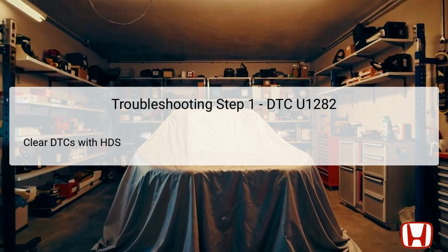Clearing DTCs prepares the vehicle's system to run a fresh self-check upon restarting, making it easier to identify new or recurrent errors. Be sure to connect the HDS properly and follow the prompts to ensure that all codes are cleared effectively. After clearing, the next diagnostic steps can be undertaken with a clearer understanding of the current system state.